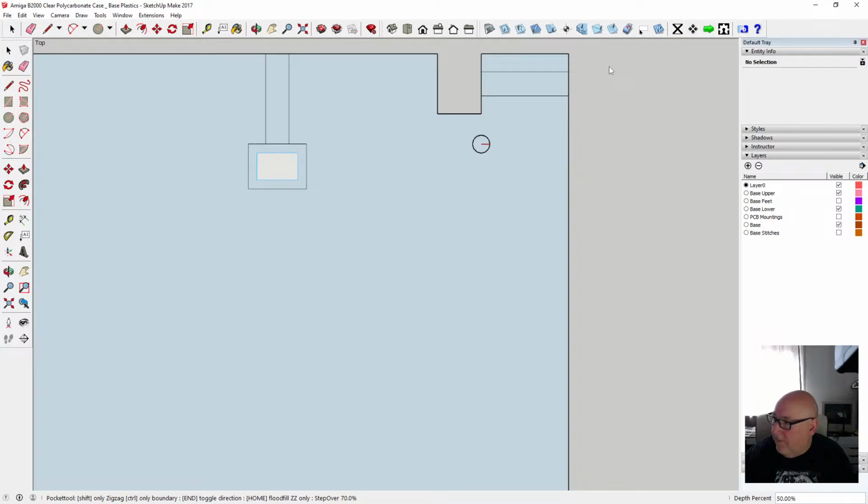But see down the bottom right hand corner it says 50% depth. We need to tell it it's not 50%. It needs to be depth of 33%. Or let's just say 6 mil. Needs to be 2 mil deep. So that's 33 1/3%. So let's just say 33%.